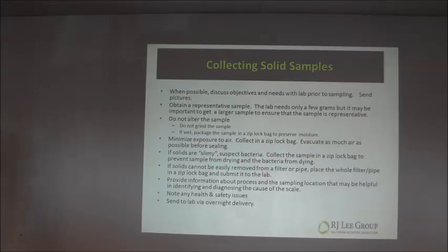If it looks like GAC, suspect bacteria. All right, and this is more prevalent, I think, in the industry than most people would like to admit. Again, collect the sample in a Ziploc bag. Prevent it from drying out. If it dries out, again, you have a chance of killing the bacteria. Okay. Try to get to the lab pretty quickly. Again, so that they can identify the bacteria that are there and give you an idea of what you